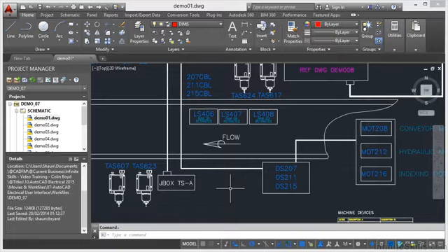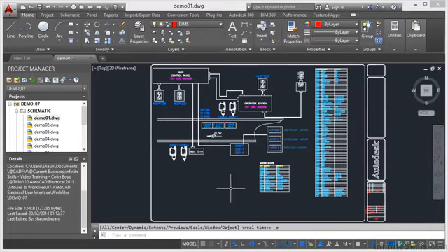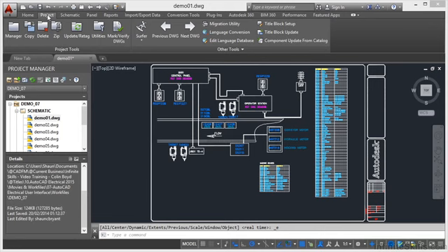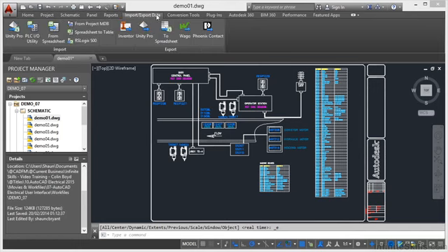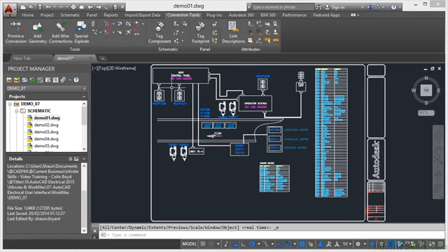If I just double click on the wheel and zoom extents again, as you can see, the rest of AutoCAD Electrical 2015 is pretty self-explanatory. The ribbon is self-explanatory, but you have AutoCAD Electrical specific tabs like Project, Schematic, Panel, Report, Import-Export Data, and Conversion Tools. So you can see all of those are specific to AutoCAD Electrical. The other new thing in the interface is you'll notice that the status bar is very different to older versions of AutoCAD. Gone are the buttons with the words on, it's all icon driven now. So make sure that you're aware of that as well when you're using AutoCAD Electrical.